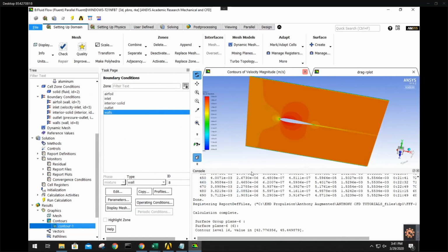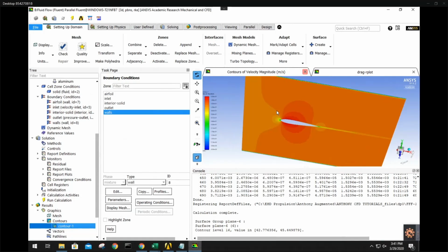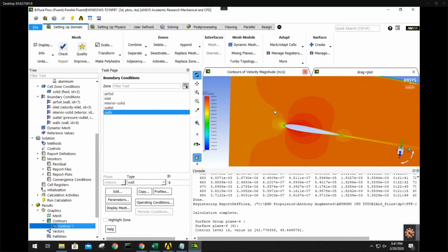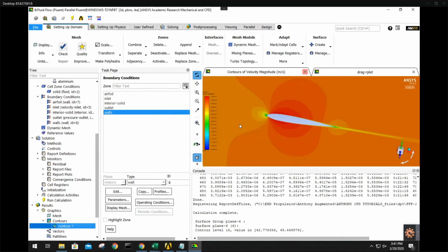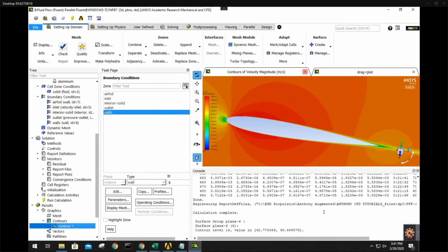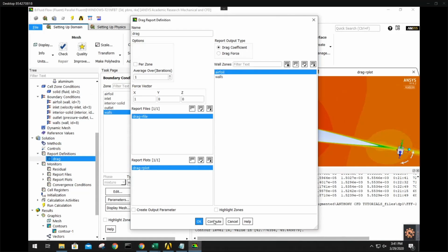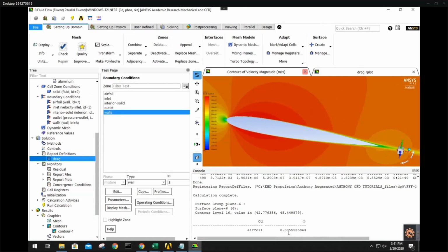So actually, it might not be fully converged because this total outside should not have a difference. And right now there still is a difference. And drag wise, I think drag is lower than expected. Yeah, this is lower.